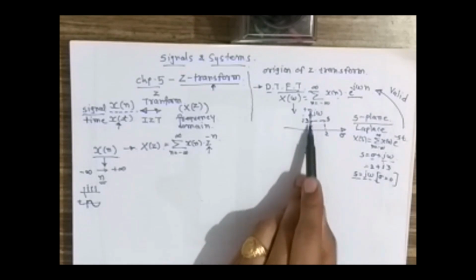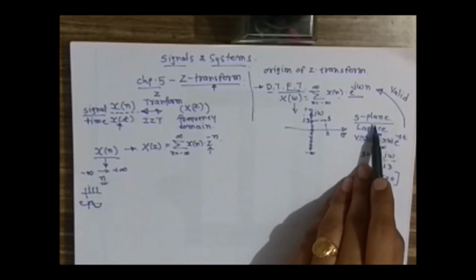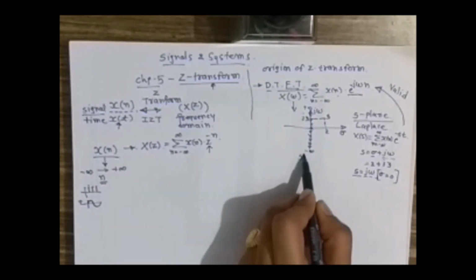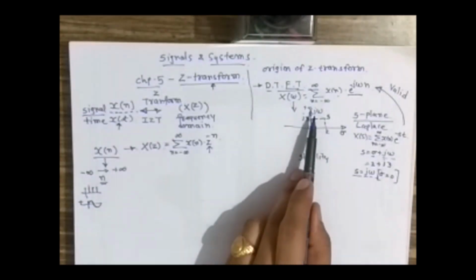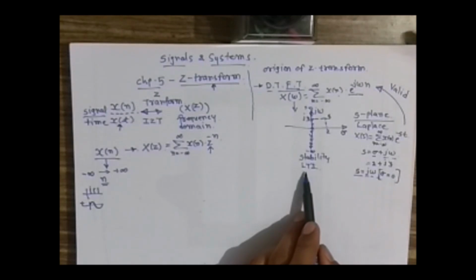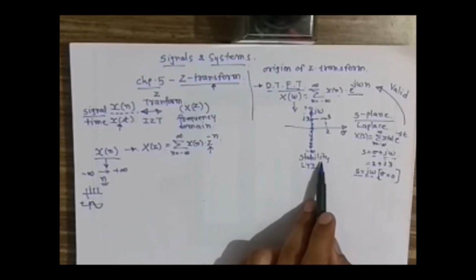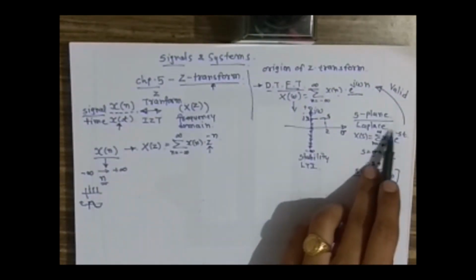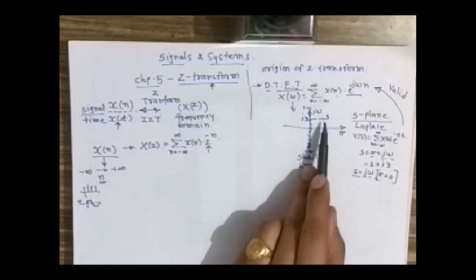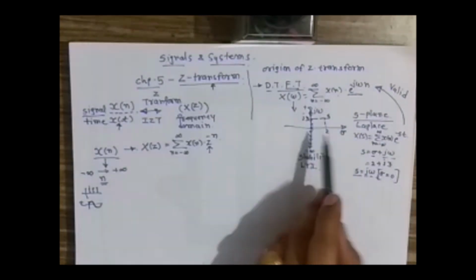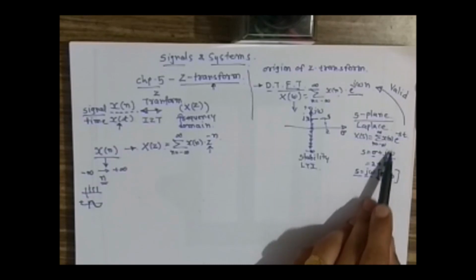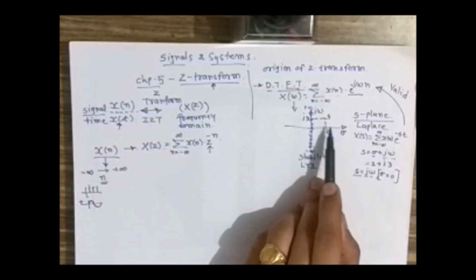As we discussed, the j omega axis is the subject of interest in the S-plane. If we recall the Laplace transform, the j omega axis has a second advantage of stability. It also comments on the stability of the LTI system that we discussed in chapters 2 and 3. LTI system is a linear time invariant system. The stability criterion in this complex domain, as per the Laplace transform, is: if any pole strikes the right hand side plane, the right hand side of the j omega axis, then the LTI system is going to be unstable.